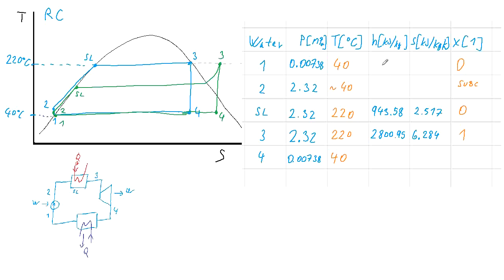And we can also get the values in the same manner at the point 1. Either from the diagram we get the value at the saturated vapor and the value at some specific steam quality, or we use thermodynamic functions where the input would be the steam quality 0 and either pressure or temperature.